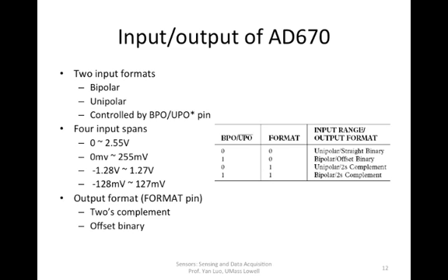First scenario is called bipolar. You have the ground signal, but you can have a voltage that swings across different polarity. You can go above this 0 volt, you can go below, or negative volts. So bipolar refers to the fact that this input signal can go positive or negative.